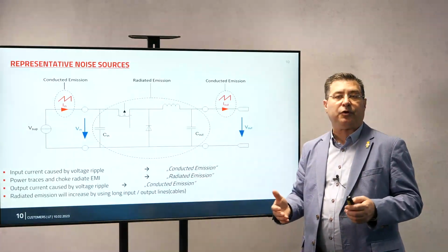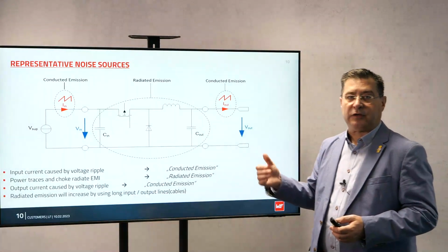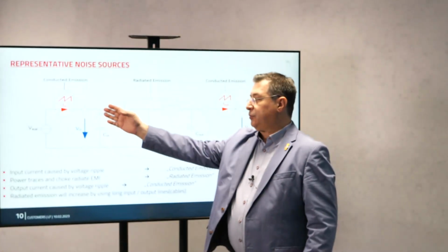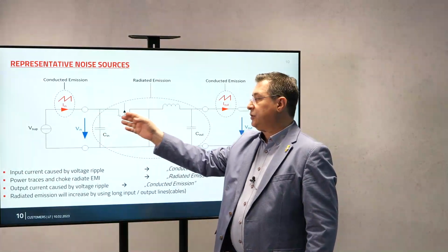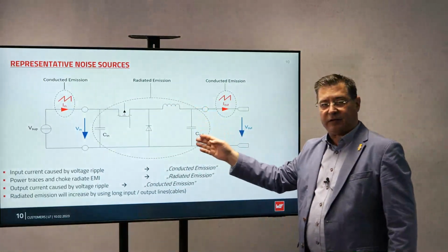If you use a simple non-synchronous buck converter, it is always noisy on the input. Why? You charge the energy into the input capacitor, and through the switch and storage inductor, you put this charge to the output capacitor.